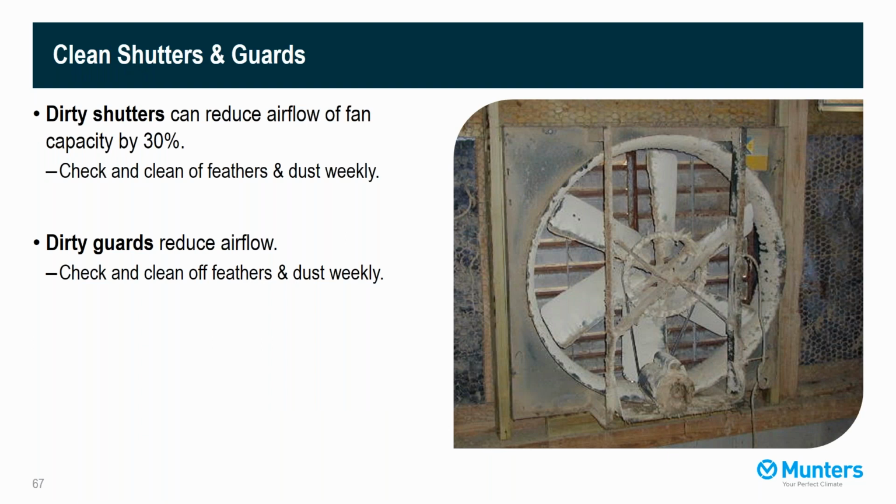We want to clean the shutters and guards. Dirty shutters reduce the airflow of the fan, so clean off feathers and dust weekly. Also, clean the guards, because the guards will reduce the airflow as well.